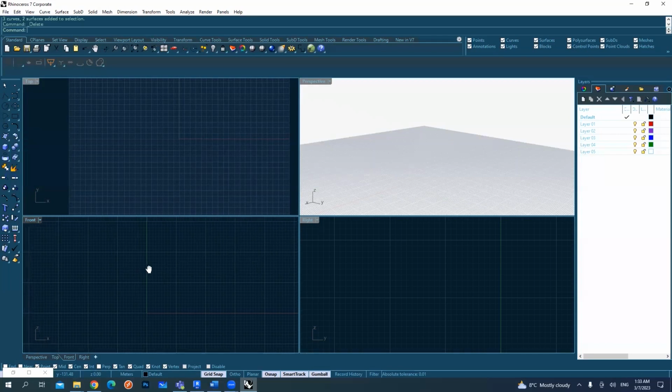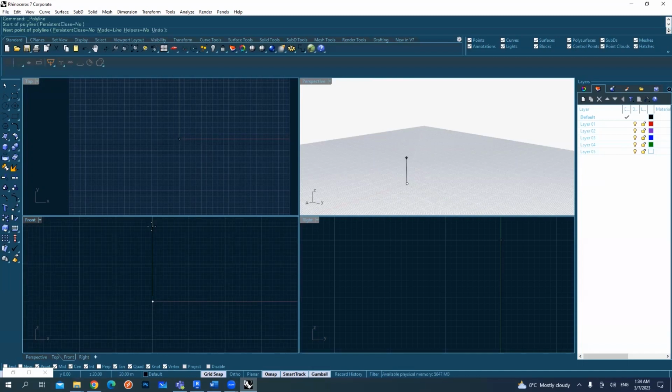Before I go to revolve, I would like to create my lines. To create a revolve, it will ask me for a profile, the exterior profile that I want to turn, and one axis in the middle. For the axis, we can create it with the polyline, which is a straight line. In the front view, a side view, I also activated this grid snap, so it snaps to the 0, 0 point, you see. I just created a straight line, maybe many units above in the Z direction, and say enter.